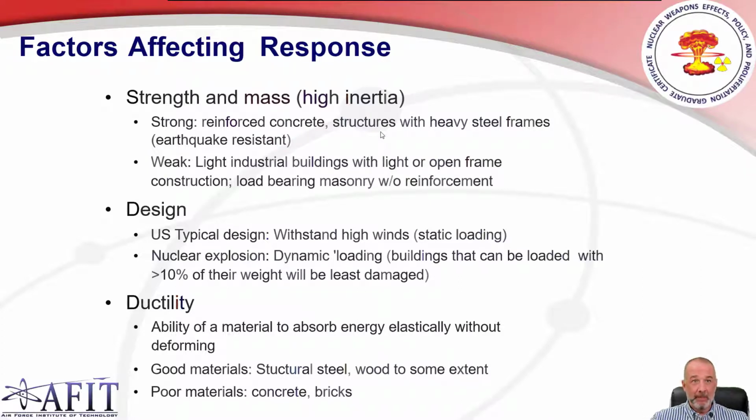So now that diffraction loading causes an area of high pressure within the building as it's trying to equalize. But then after everything has passed and now there's lower pressure outside, you could very possibly get forceful ejection of everything inside the house or the building.